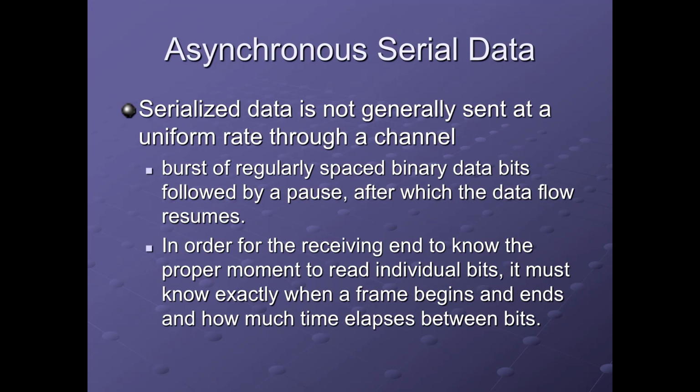What we would all be working with is asynchronous serial data connections. These are connections where the actual synchronization that is necessary for any data link is embedded in the same stream or serial train of bits. The synchronization is right in the data. So this is called asynchronous serial data. Serialized data is not generally sent at a uniform rate.